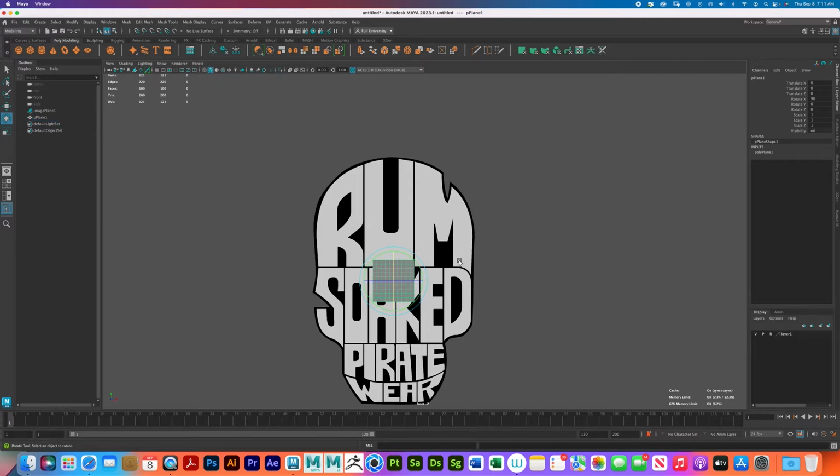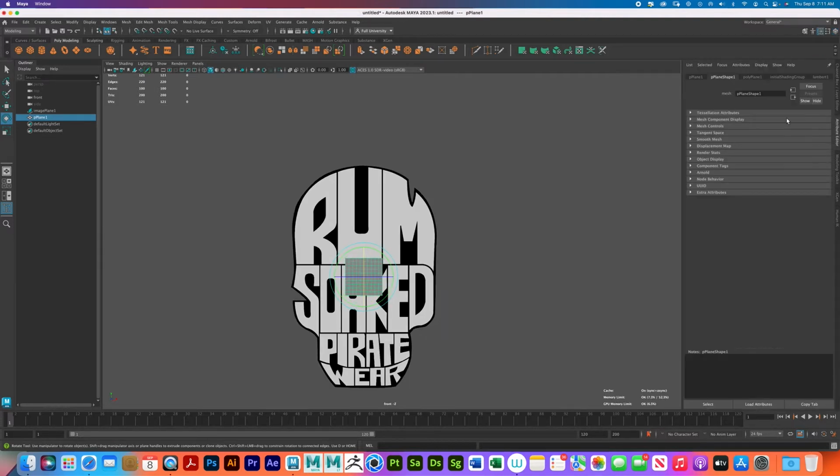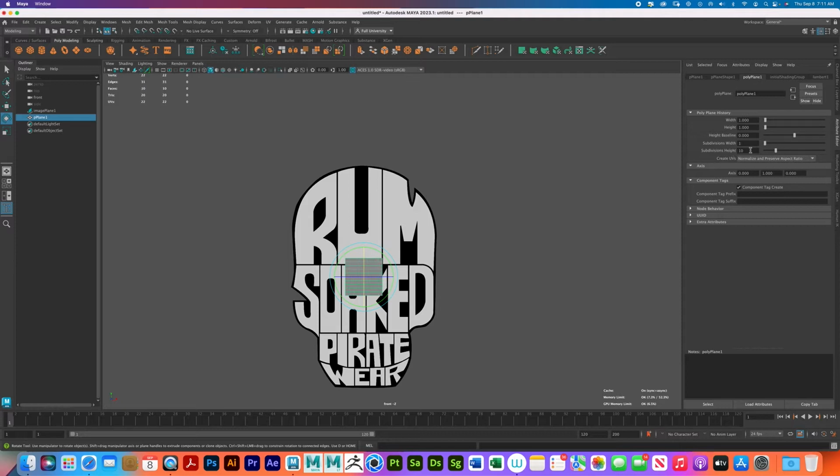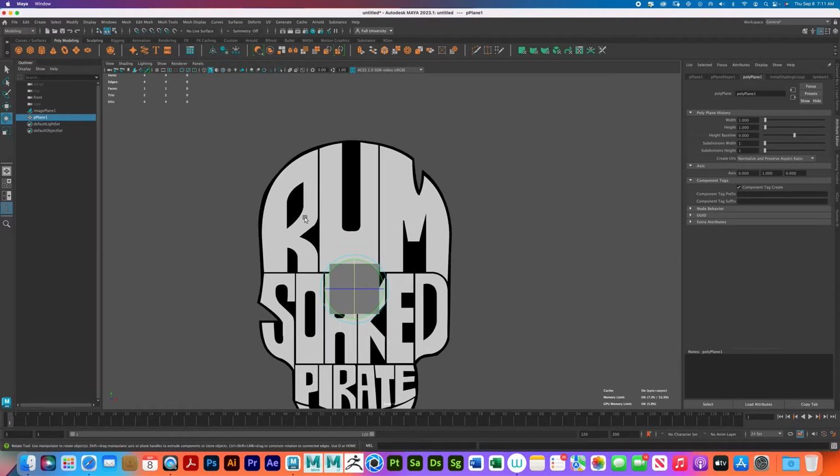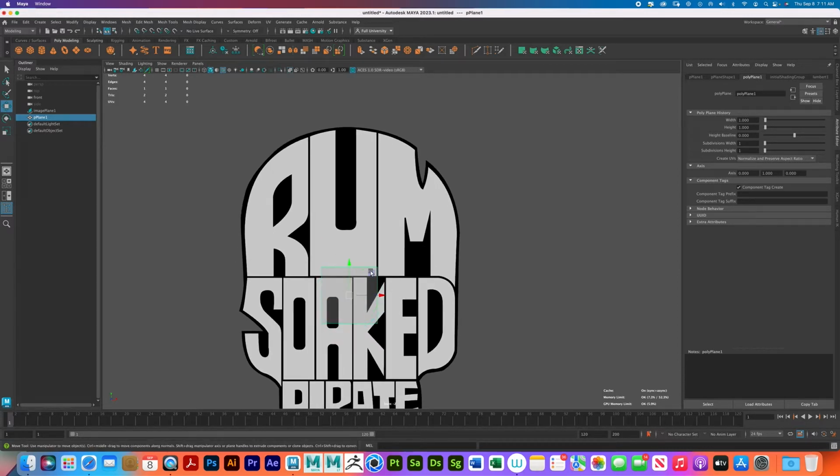The next thing you want to do is click on it. Come over to your attribute editor, take the polyplane, and get rid of the subdivisions here. You don't need that right now. And important, for you to be able to see your work, you have to come to shading and turn on X-ray. I'm also going to turn on wireframe on shaded because sometimes it helps me see where things are going. Now that that's set, I'm going to press W.